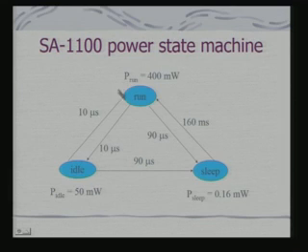In fact, this state machine is to be used by the controlling software, which in many cases would be the operating system, to decide about the different states in which the processor should operate, based on maybe the load as well as the usage pattern. And there are other strategies also by which, even without involving the OS, switching into different power states can be done.